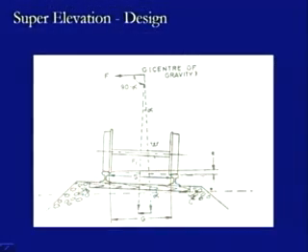Here the same thing is being tried to show. Here the section is as shown previously. This is the slanted condition where the outer rail is up and inner rail is down by a value of superelevation E, that is a small e shows this superelevation value. Here when we look at the weight component, then the weight component is acting vertically downwards like this. This is the weight component, and the centrifugal force will always act horizontally in the outward direction. So, the centrifugal force is acting horizontally in the outward direction like this.